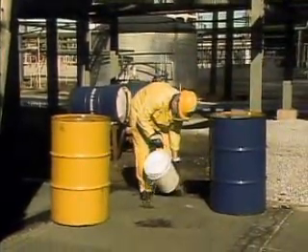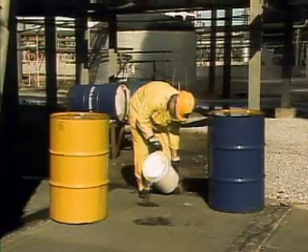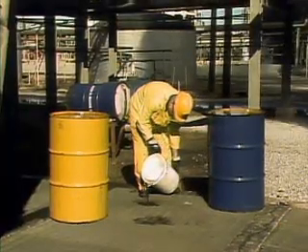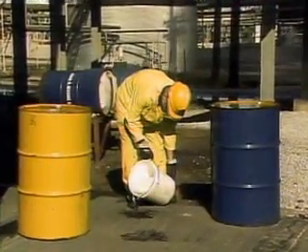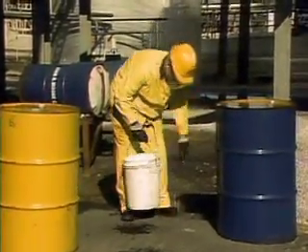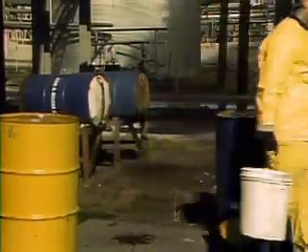Now, chemicals aren't always added with specialized equipment. Sometimes you have to add them by hand. If that's the case, you'll need to follow your company's procedures about where and how the chemicals should be added. For example, you may be required to add the chemicals near the makeup line so that they can be thoroughly mixed with the cooling water.